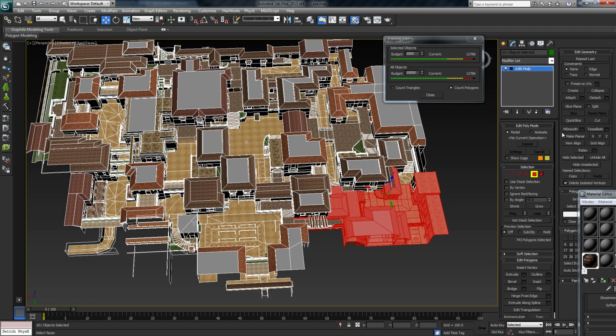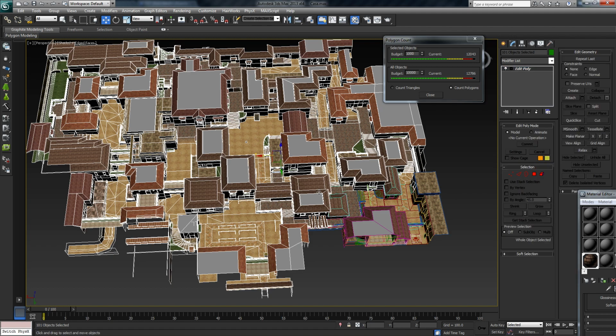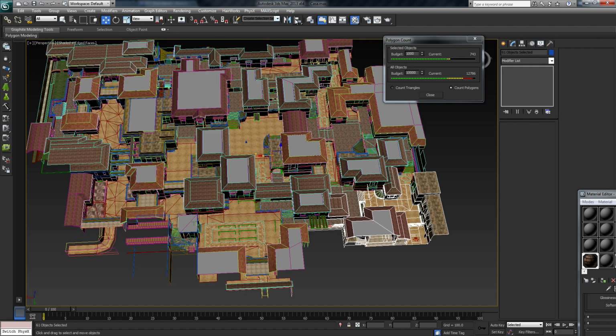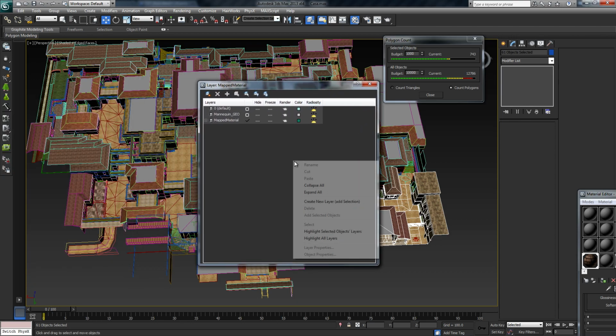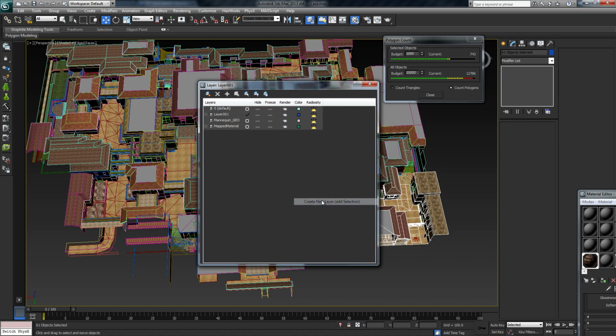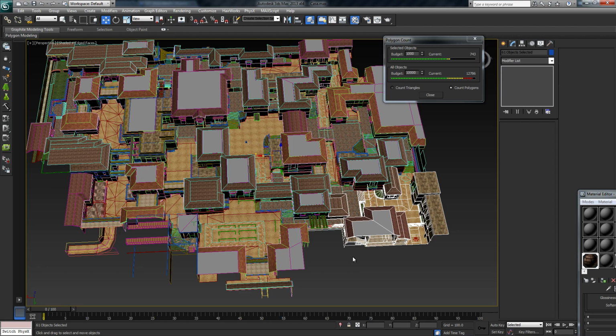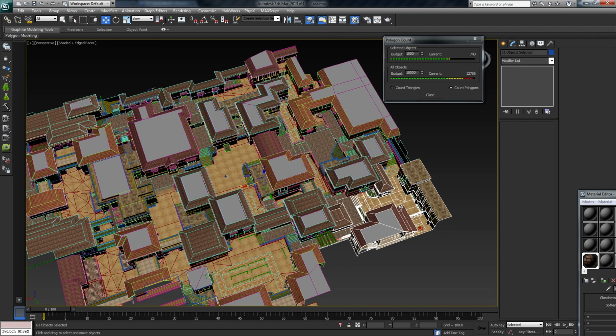Say we want this to be a block, and then we can do a detach, and then we can do an invert selection. That should keep our bulk selection. We can do an invert selection, and then we just go ahead and put that on a layer. Bring the layer over here, and we'll call this, for example, create new layer, Building 1. So now we can export this as a complete buildings selection, maintain our material connection to it.